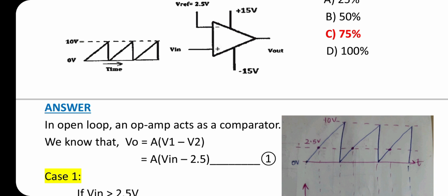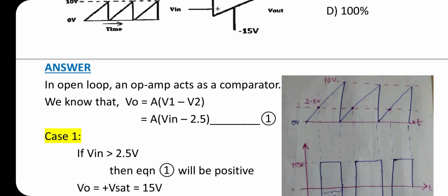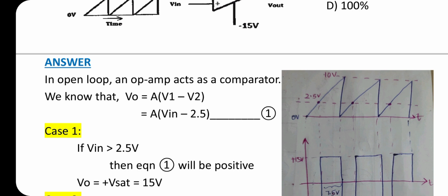Actually, duty cycle is the ratio of the time a load or circuit is on compared to the time the load or circuit is off. The duty cycle, also called duty factor, is represented as a percentage of on time. A 60% duty cycle means that the signal is on for 60% of the time and off for 40%. Therefore, the equation for duty cycle is equal to T on divided by T on plus T off.